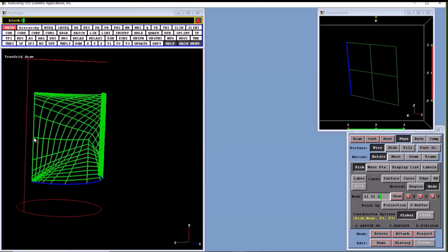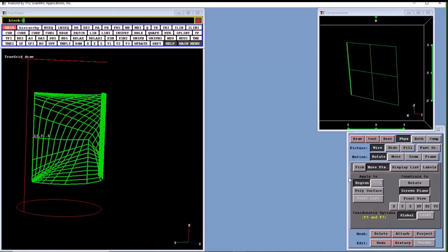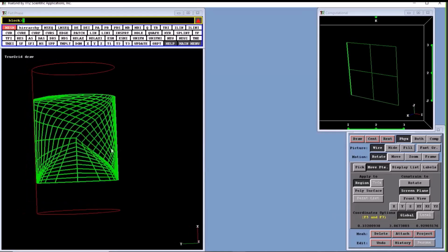It is required that it follow the algorithm that distributes the nodes. So it is not movable. If I were to try to move that, you will see it'll still bounce right back. Because it no longer has any degrees of freedom, just like in finite elements. All of the degrees of freedom have been consumed by the constraint that says they have to follow that rule for nodal distribution. And the same is true for this vertex.